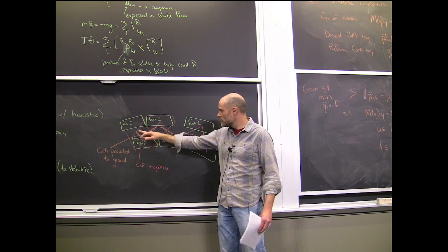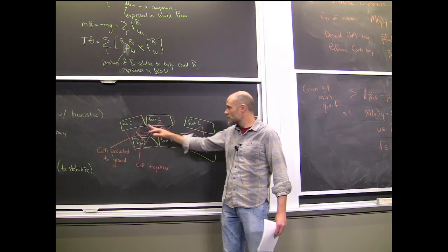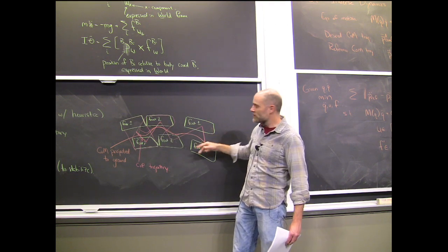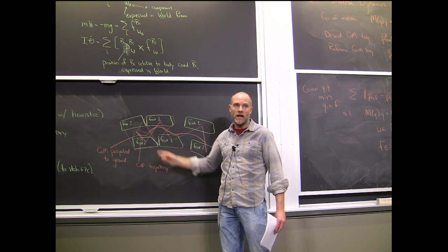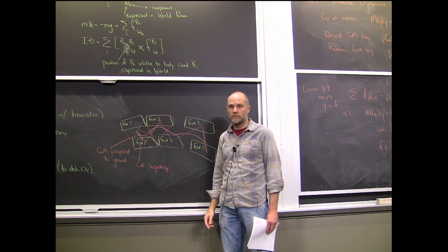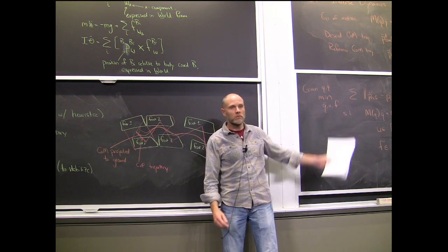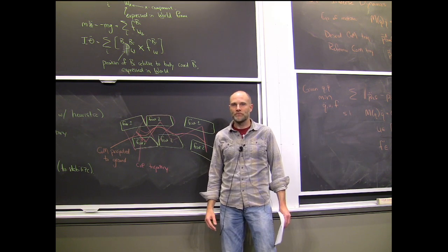If we just naively took the original center of mass trajectory, differentiated twice, and applied that acceleration, then we would do something over here, right? So it's just a little stabilization term to command an acceleration that will get you back to your nominal trajectory. The Kp is probably 1 or something, a simple diagonal matrix.